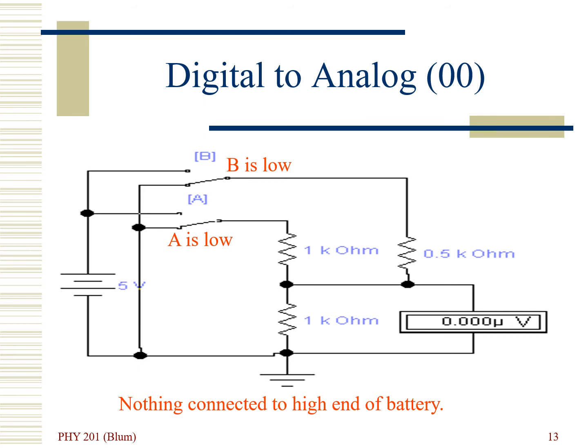Okay, so we're putting in, in this case, a low input, and so there is no voltage coming from switch A, and there's no voltage coming from switch B, and so then, of course, the reading is 0 voltage. So that's easy to understand, but it's one of the 4 states we need. We are looking for, if we put in low, low to get a 0. If we put in low, high, we are looking to have 1/4. If we are putting in 1, 0, we're looking to have a half. And if we're putting in 1, 1, we're looking for 3/4. So I have to convince you of 4 different states, and so far I've convinced you of 1.